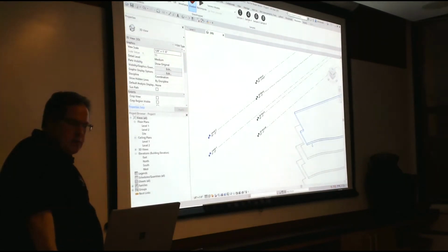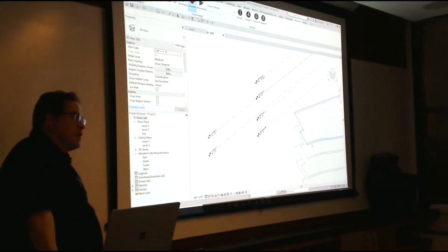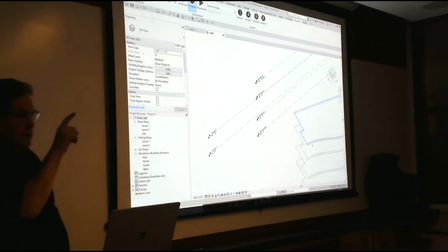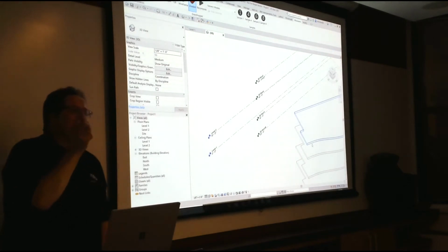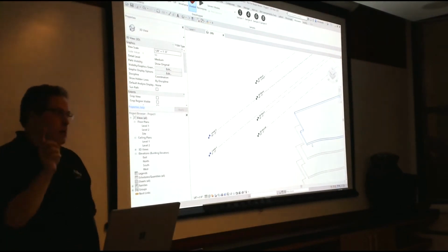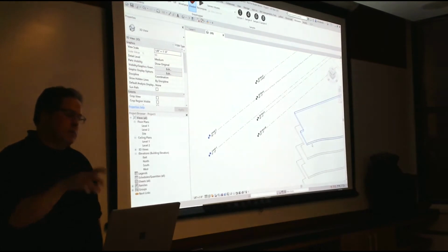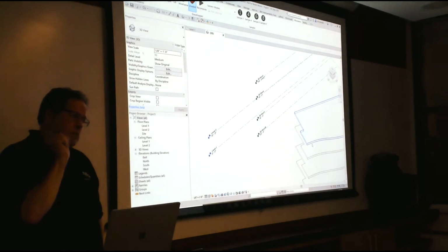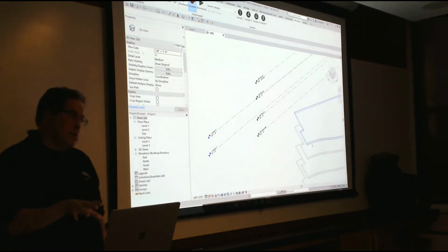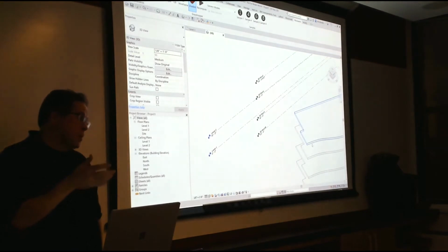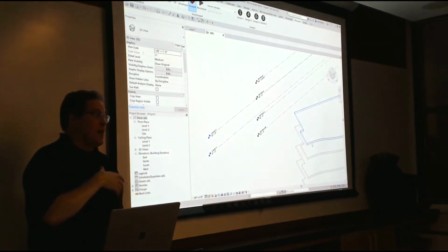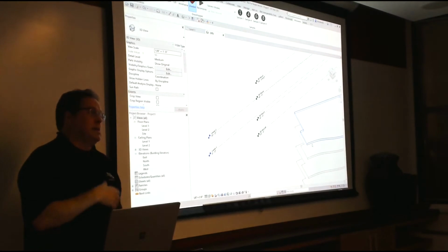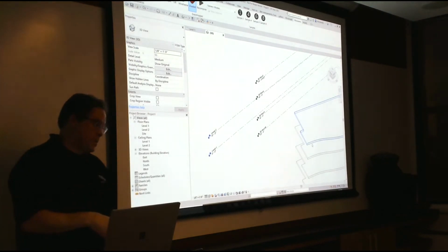straightforward? There are a series of plugins that are coming down the pike, for instance, like Conveyor from Nathan Miller. And what it does, it's based on this technology. And what he has is one where you can create your mappings between, let's say, layers and different object types and names and sublayers and all that stuff. You set all that up. If you draw it properly in Rhino, it will all come into Revit using this technology, but mapped properly. Nice part about that is you could save it. You could have it as your standard, and that would work. Right. That's one way to do it.